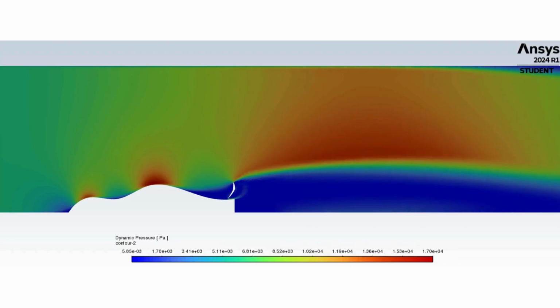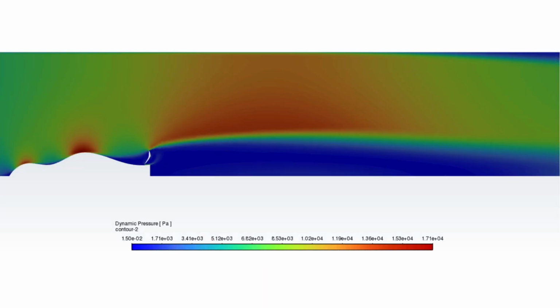The dynamic pressure plot indicates higher pressure beneath the wing and slightly reduced pressure above it. The pressure difference is more prominent, showing an optimized aerodynamic configuration for braking. Increased downforce enhances stability and grip during braking, ensuring shorter stopping distances. The higher pressure drag resistance to airflow may slightly reduce the car's speed.